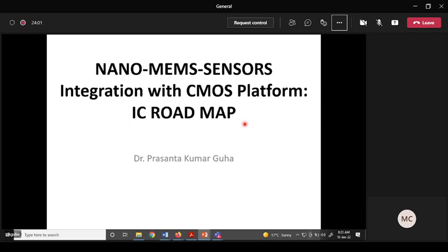So that is one aspect, and in another aspect, people have been looking for other materials, other structures. For example, MEMS, micro electromechanical system, is a different kind of structure compared to conventional IC or conventional CMOS process. And there are sensors and other nanostructures, nanomaterials, for example non-silicon materials, graphene, MoS2, tungsten disulfide WS2, molybdenum disulfide, and so on and so forth. They have carbon nanotube. They are non-silicon materials, and they do not have their space directly in industry. To be honest, directly in industry means directly in the CMOS industry.